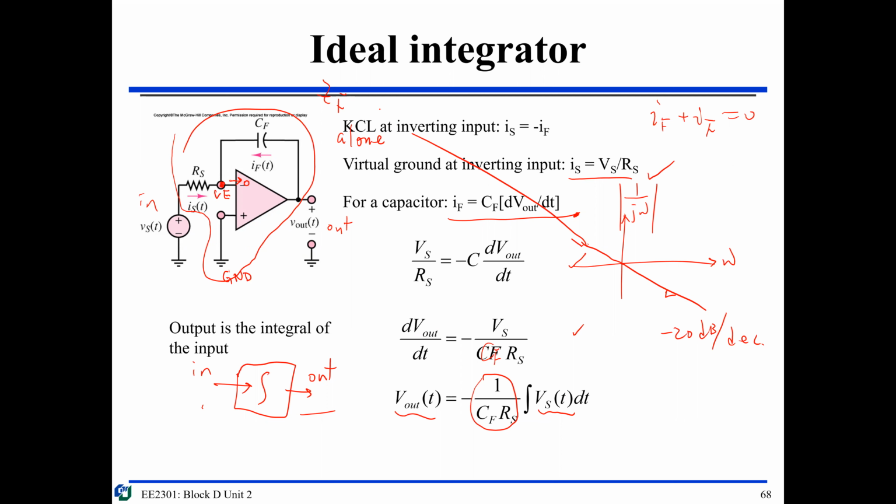That means if you have a DC bias, a DC signal, it will get amplified hugely. The integrator makes a control system that suppresses your bias. If you have a constant bias, a direct current bias, it keeps adding together to suppress it and makes the bias go to 0. We are going to mention this later.